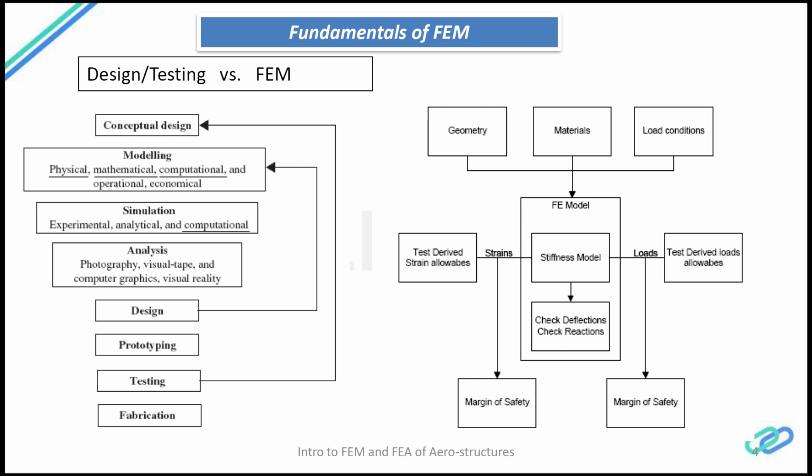On the right, you can see a finite element model, which is the mathematical representation of the actual physical structure, where we give in geometry, which is the geometry properties, your area, moment of inertia, and the dimensions. These things go into the geometry input.